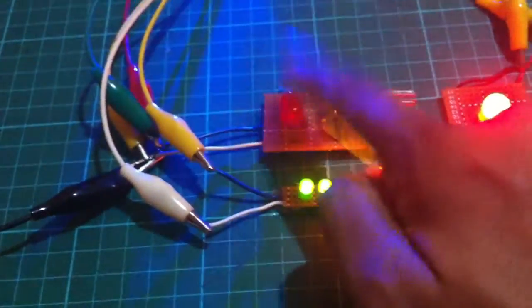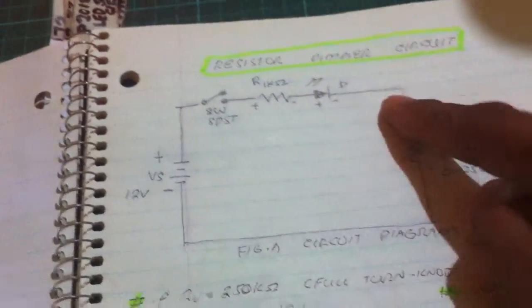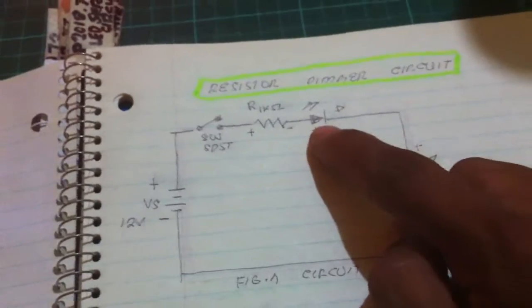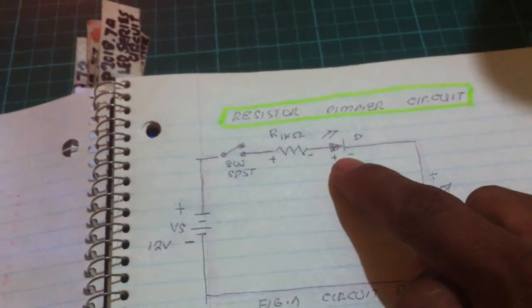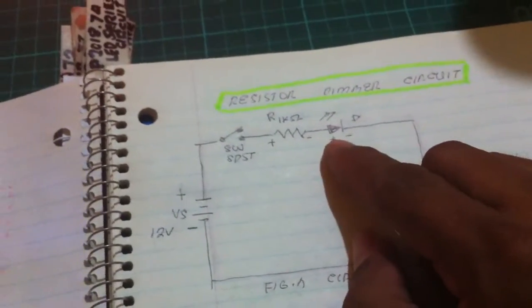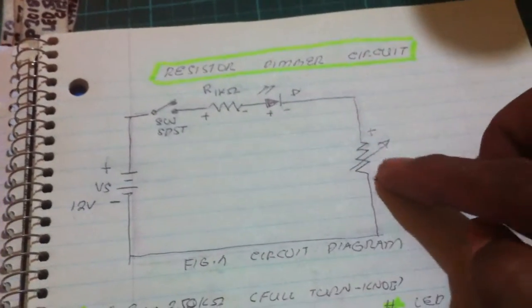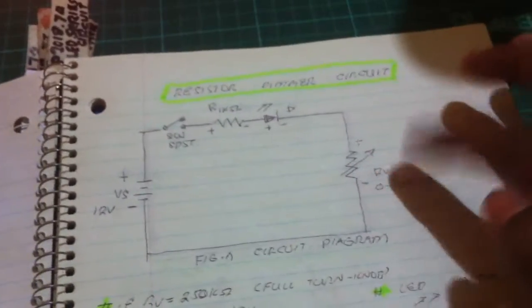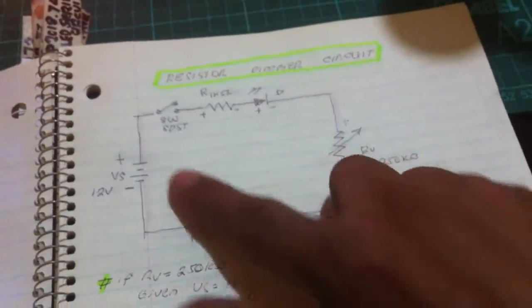It's not completely turning off, and the total current flowing here is 0.0004, not enough to turn on this LED. And then also the voltage here is just 0.04. So this LED will not turn on, since all the current is dissipated here at the variable resistance, very big resistance, 250 kilo ohms, but still the current is flowing here.